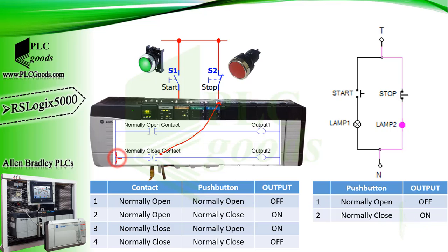In this case, like the industrial circuits, the virtual power reaches this contact. Note that this push button lets voltage appear at the digital input. So, the PLC changes the state of this contact and opens it. Thus, at the beginning, or normal conditions, the output will be off, because the virtual power won't be able to reach the output. Try to understand the other states. You will see, if all used push buttons are open, the PLC program and the right circuit will have the same logic.